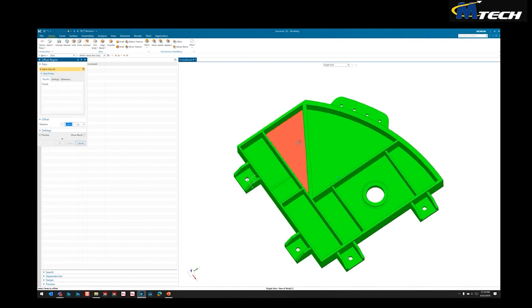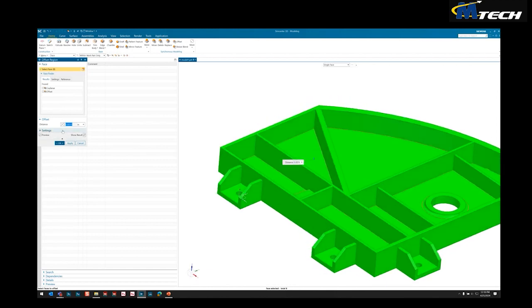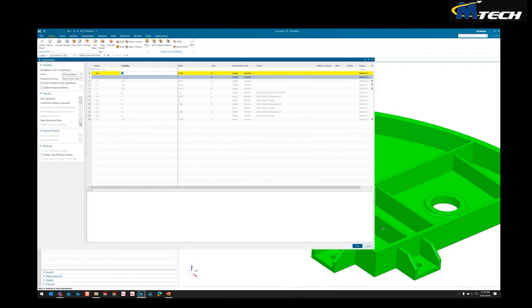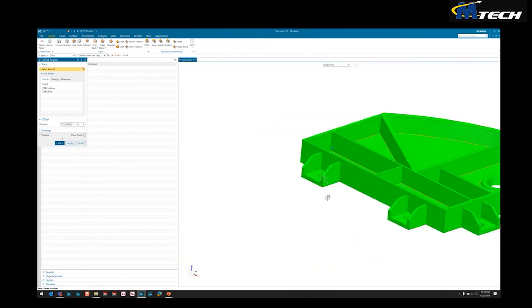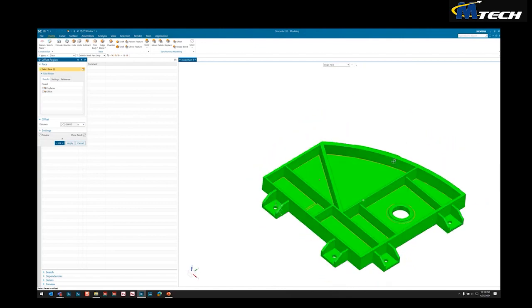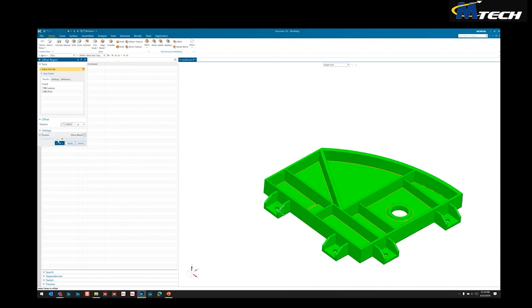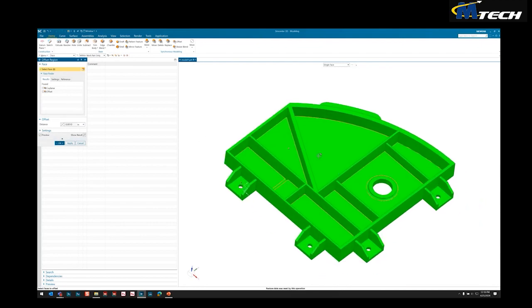So next, we're going to offset the thickness of our web. All right, so now our arrow is pointing up, so we need to reverse it. We want to remove thickness that's going to be equal to T1. If I zoom in here, you can see that this is going to be offsetting this face towards the exterior. And each time it updates, it's going to either add or remove thickness based on our value. In our case, adding a positive value is going to be reducing the inside face thickness.